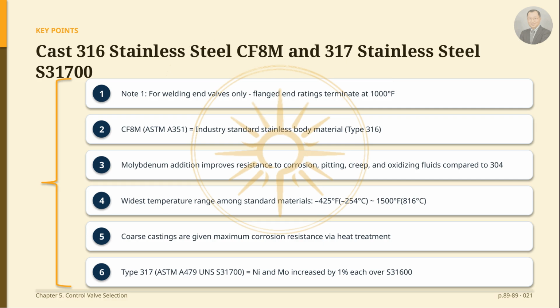Now, I'll introduce cast type 316 and type 317 stainless steels. First, to revisit Note 1 from the previous table, those values apply only to welding end valves, and flanged end ratings terminate at 1000 degrees Fahrenheit.